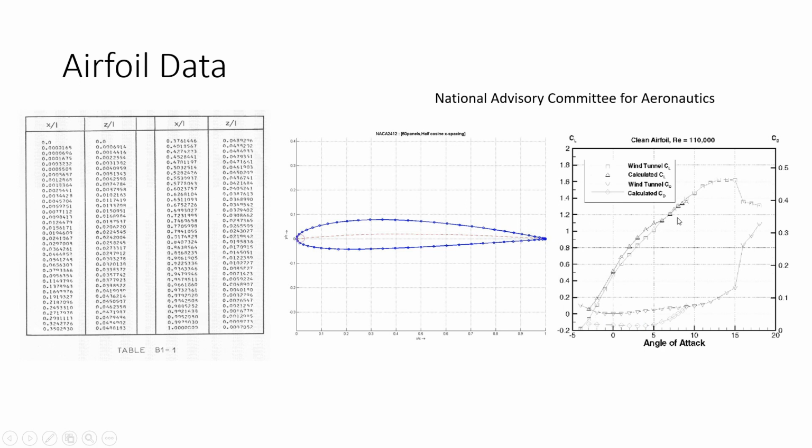Firstly they design the airfoil, and this is the structure of that airfoil, and this is how it behaves for different angles of attack, and what the CL and CD are. Since they are divided by dynamic pressure, they directly relate to the flight velocity.